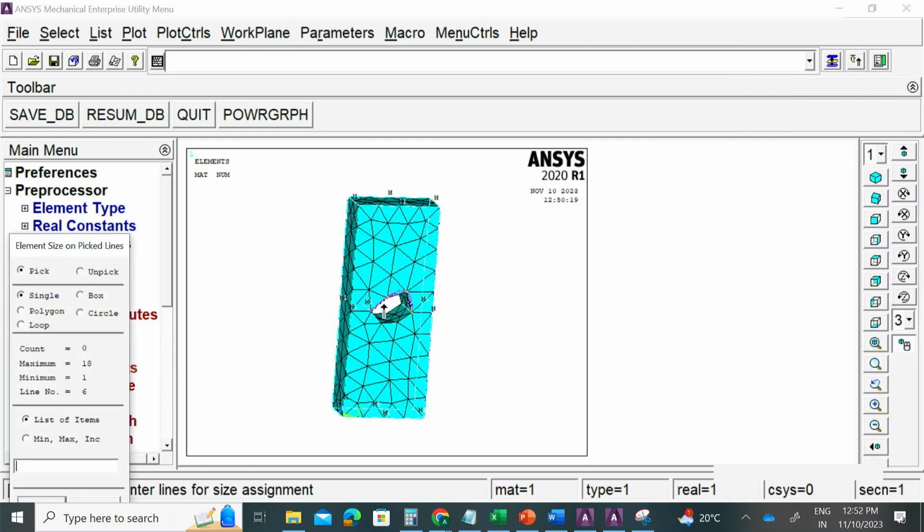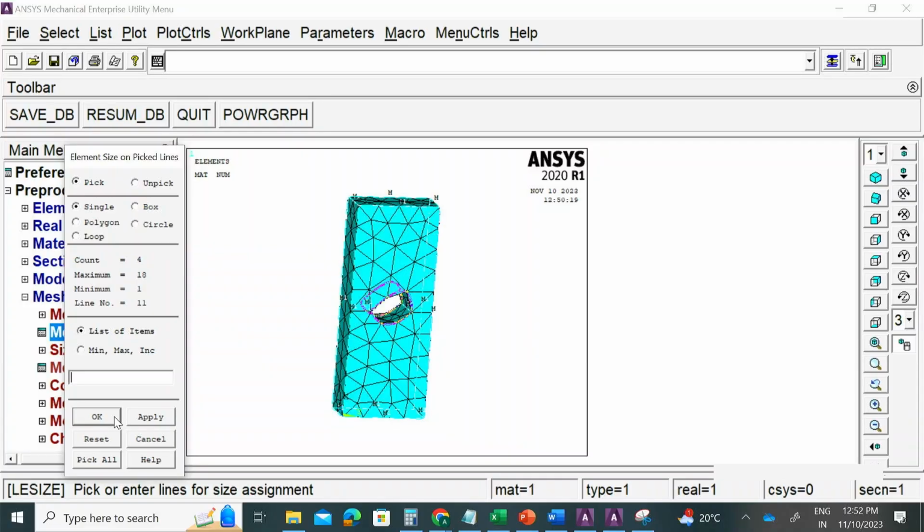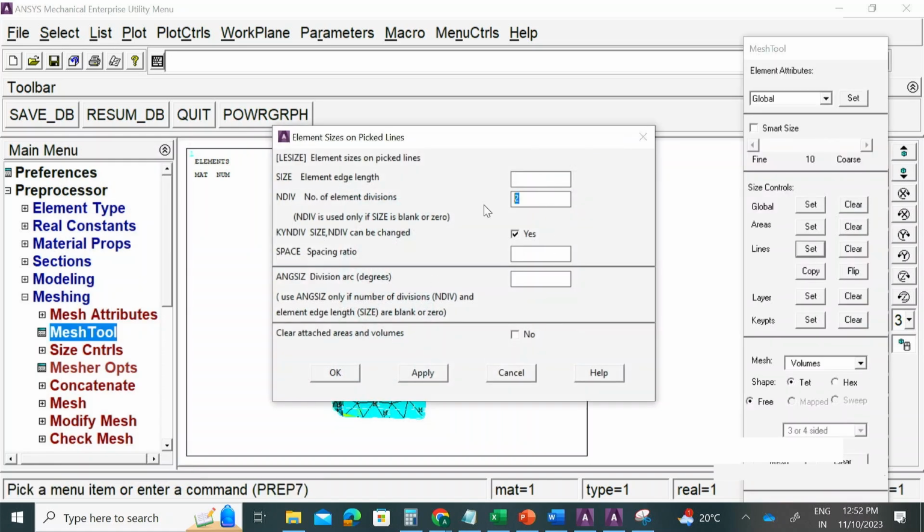how these are going to be divided. So there is one spline here, one spline here, one spline here, one spline here. How do I want to divide them? So let me divide them by maybe 5 divisions, right? They're a little wide, they'll open up to be at least as big as this. So I want the mesh to be as smooth as possible, right? The goal is we do not want a mesh which has a huge element followed by a very small one. We want a nice transition from the larger elements to the smaller elements, right? So I'm going to break this to 5 divisions, right?